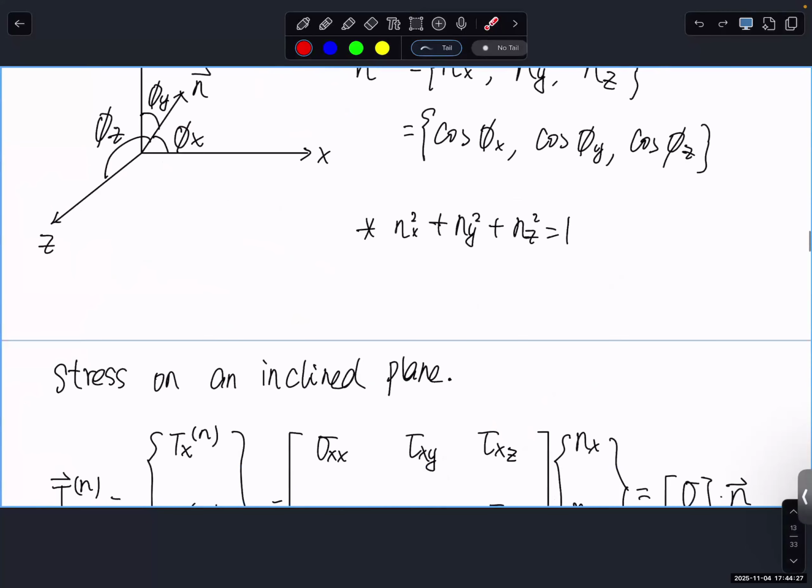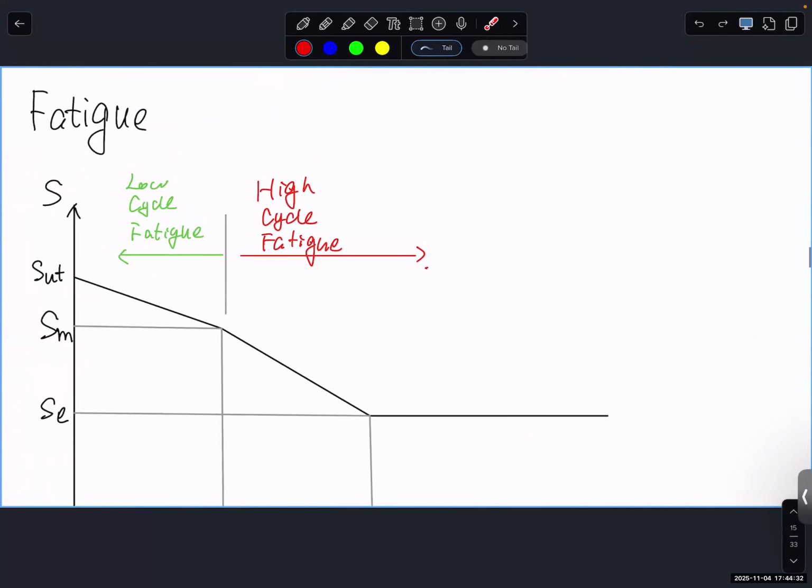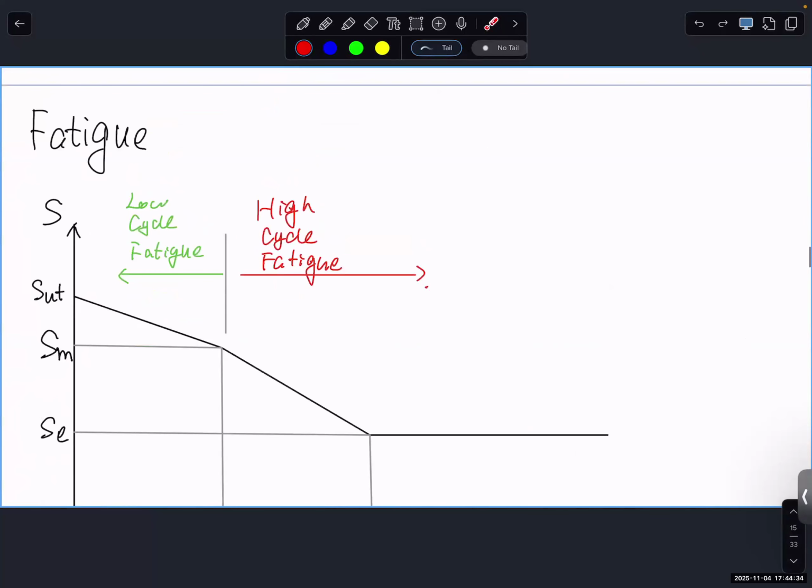In the meeting last week we talked about the muscle open position and closed position. That's a different topic. It's basically a fatigue problem. I would imagine the open position generates larger stress, because if you have a spring system and elongate it more, it has larger force and larger stress. In the closed position, the elongation is much smaller and the force is much lower.